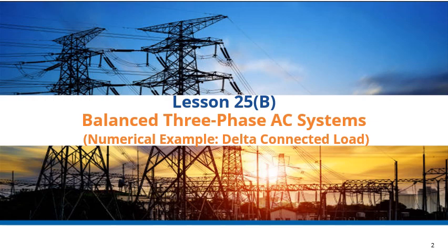Just as in lesson 25, I will be calculating for this system the line and phase voltages, real and reactive load power consumption, real and reactive line power losses, power factor, efficiency, and voltage regulation. In lesson 26, I'll use the example of this lesson to show the application of capacitors in raising load power factor.